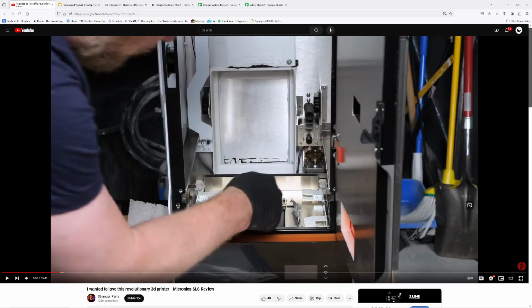So remember I said they use halogens to lift the temperature of the plastic above a certain level, right? So it lifts the plastic to right below its sintering temperature, and then the laser knocks it over. So now you're having a user install these bulbs, I'm assuming to prevent damage in shipment, right? Number one, you can have the user damage it, and so now the machine is basically useless, because the laser does not have enough power, watt density, to melt the plastic without it being right up next to the sintering temperature.